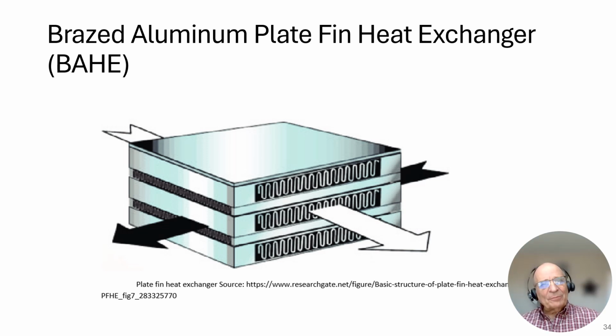And hopefully, at the end of that process, there are no leaks associated with it, because it's then tested for pass-to-pass leaks or any other type of leakage. Like, for instance, if you had leakage on the outside, it would show in this area here. And these can be made counterflow, cross flow, parallel flow, whatever configuration is needed has to be designed, then specially manufactured, and then sent out to the customer for use, of course, after testing.